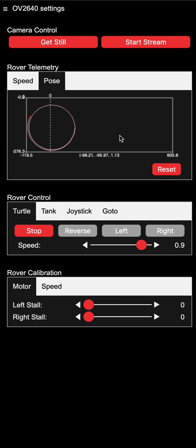If you want to drive in a straight line, the motors need to go at the same speed, and therefore you need to do some software work to give the right PWM value to the left motor and the correct PWM value to the right motor, so they drive at the exact same speed. Then the rover can go forward. And that's what's called speed control. In the next video, we'll talk about calibrating the rover, such that when we give it a speed, both of the motors will drive at that same speed.